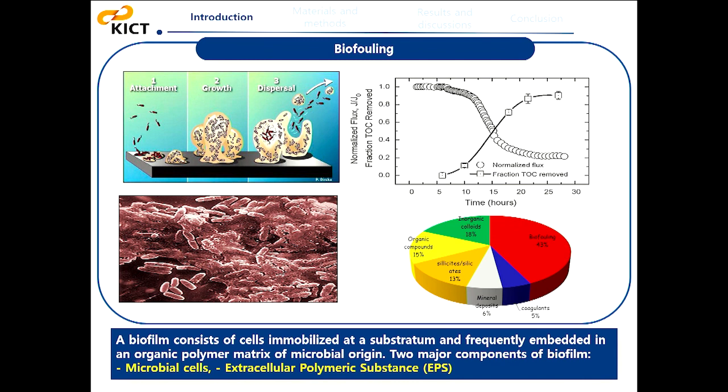However, biofouling is a major contributor to the increase in operational cost of membrane processes because it increases pressure requirements and chemical use and decreases water fluxes. Biofouling generally occurs from biofilm formation, which are surface-bound complex microbial aggregates encased in cell-produced extracellular polymeric substances that are primarily composed of polysaccharides and